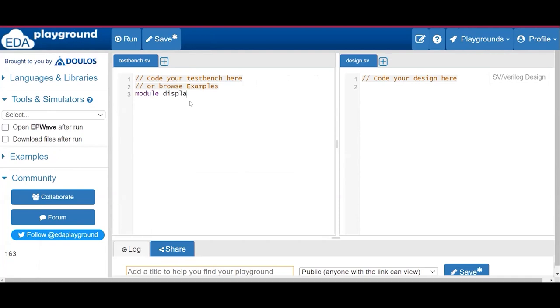For the display statement, we can write some variables, like a reg variable. The reg variable is of 3 or 4-bit size. Some variable name, say address, and initial begin. Address equal to 20 or address equal to 8, because within the 4-bit range we can take, right? So I'm doing $display here.